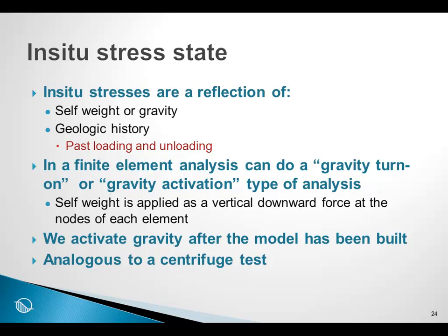In this sense, an in situ analysis is very much analogous to a centrifuge test, where the model is first built and then the gravity is applied through the rotation in a centrifuge. So it's useful to think of in situ analysis as being analogous to a centrifuge test where we activate the gravity after the model has been built. This concept can also be used effectively in certain other situations, as we will see throughout these sessions.